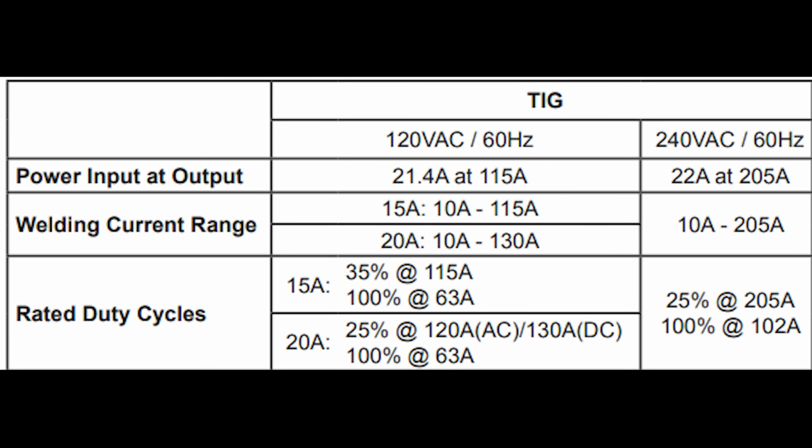Being completely honest with you guys, if your budget is at the 200 amp class machine, the most you can really expect to do any kind of volume with, without a water cooler, is going to be around 1/8 inch or 3.2 millimeter material. If you go above that, you're just going to be disappointed, especially if you have ambitions on welding 1/4 inch or 6 mil plus material. You really need to be in a 250 amp class machine, not a 200 amp class machine.